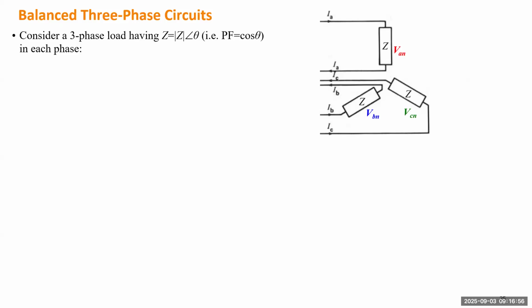So for three-phase circuits, first we consider balanced condition and the steady state condition. So in this course, we don't consider imbalance between any 2 or 3 phases, and we don't consider any contingency. So when we draw a three-phase circuit, we really mean 3 very symmetric single-phase circuits. They are just laid out with angle displacement by 120 degrees.